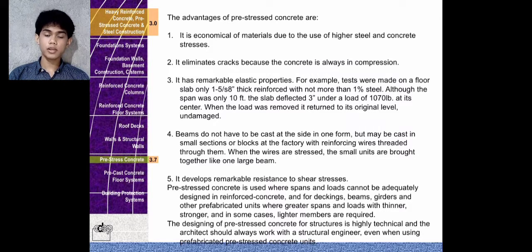And firstly, the advantages of pre-stressed concrete. Number 1, it is economical of materials due to the use of higher steel and concrete stresses. Number 2, it eliminates cracks because the concrete is always in compression. Number 3, it has remarkable elastic properties.